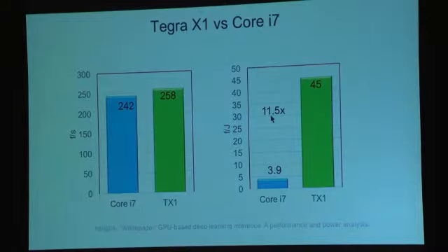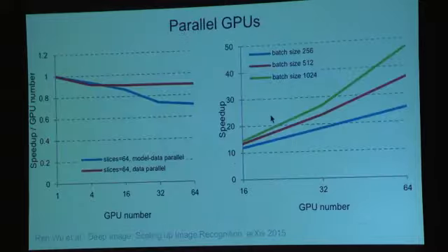We can have the vast majority of the joules consumed in a GPU go to actually doing the arithmetic operations and essential memory operations. It's almost within a factor of 2 of the total power is going into things that you have to do, you can't do without. And when I get to special purpose hardware, I'll talk a little bit more about that.